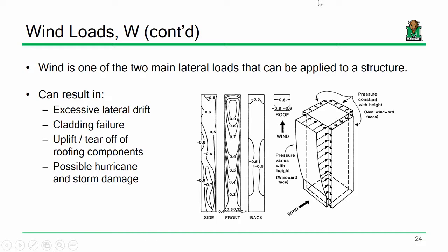This is the result of some wind tunnel testing, but in the end, the behavior works quite well. As wind is hitting the building, what ends up happening is the wind pressure gets larger and larger. Another point I'll mention, you actually can get pressures on the other ends of the building. As wind hits one side of the building, you can generate pressures on the other end. There are also some other quirky aspects with wind. You can generate negative pressures inside the building.